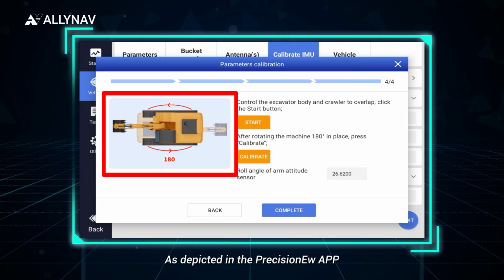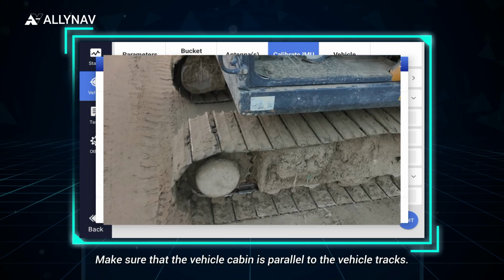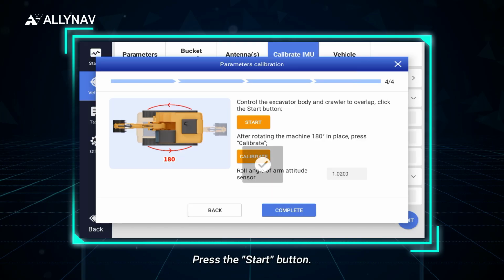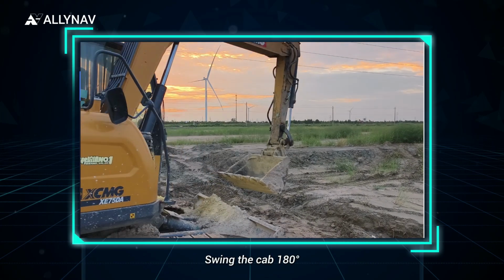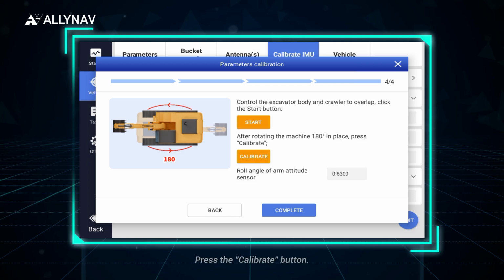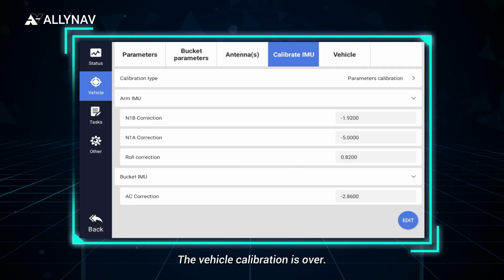As depicted in the Precision EU app, make sure that the vehicle cabin is parallel to the vehicle tracks. Press the Start button. Swing the cab 180 degrees. Make sure that the vehicle cabin is parallel to the vehicle tracks. Press the Calibrate button. Press the Complete button. The vehicle calibration is over.